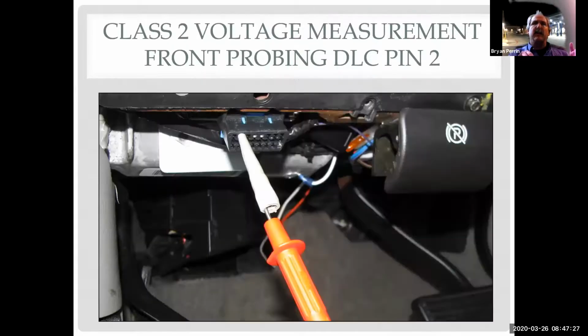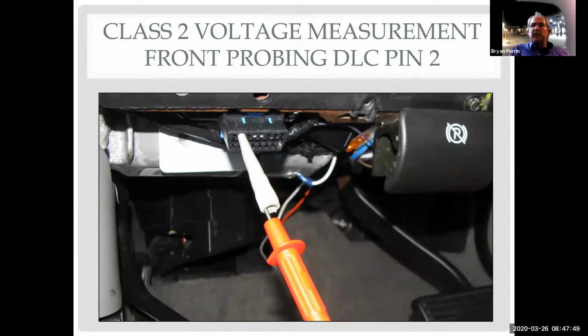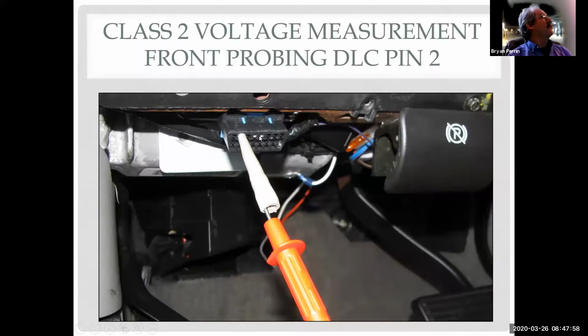And when I go to my DLC, we can see here I have several pins. You guys already looked at 3 of those pins. You looked at pins 4 and 5, and they were what? What's on pin 4 and 5? You guys just had to use it for the memory. Ground? Ground. And what was pin number 16? It was positive. That's positive power. So I can see here in the picture, there is 4, there is 5, and there is pin 16.